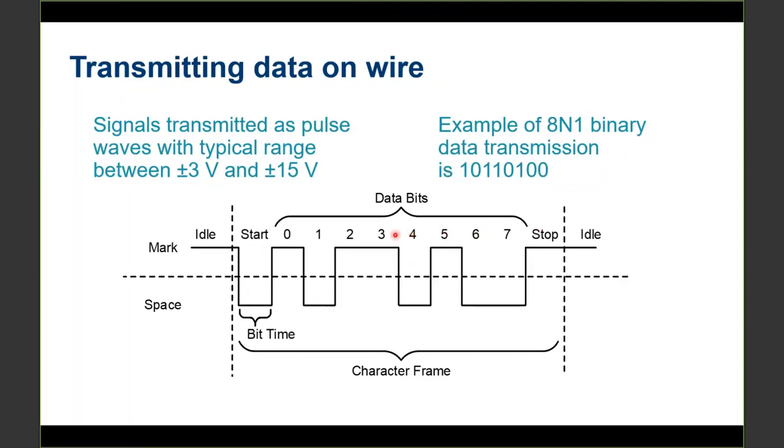Similarly, if I wanted to measure this same type of voltage on the data coming into the device, what it's receiving, we'd switch the lead from pin 3. We'd have the positive lead on pin 2 and put the negative lead on pin 5. So basically, you're taking your reference. Your reference is that ground, and its voltage should be 0. Then the transmit and receive pins are going to have a voltage that you're measuring against that reference.